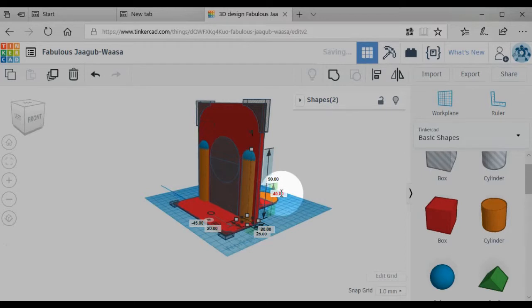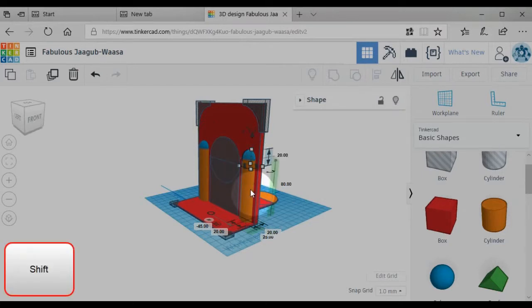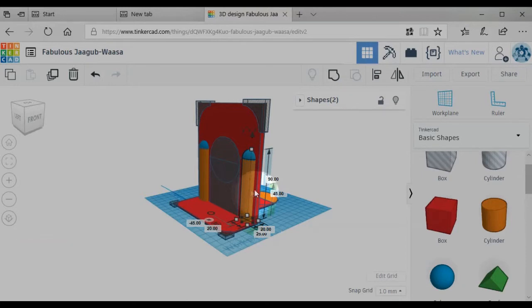The 45 mm height should be explained. The cylinder is 80 mm tall. Half of the 20 mm sphere rises above the cylinder, adding 10 mm, making the group a total of 90 mm tall. Since the group is being positioned from its center, the height is half the total, or 45 mm.